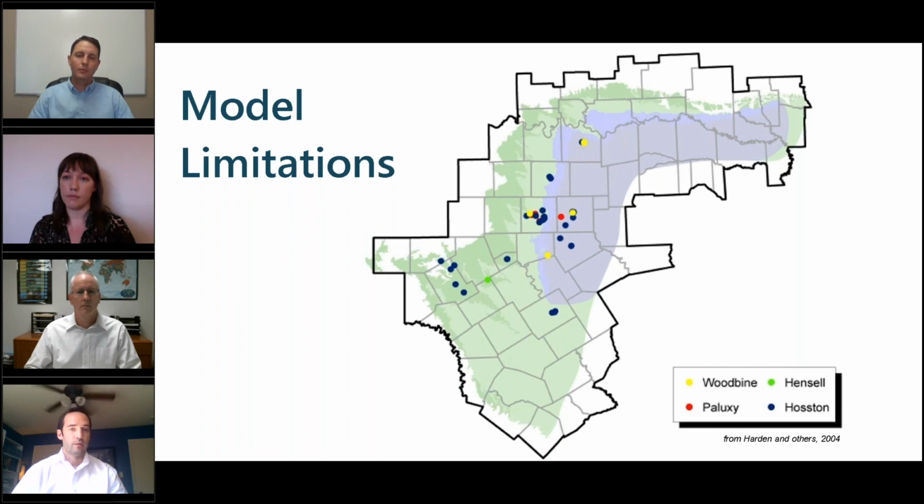So if the model is intended to forecast, say, the response of an aquifer to additional withdrawals that might affect the stage of surface water bodies in the area, then simulating a lake with a constant head is probably not going to work very well. It's probably not an appropriate boundary. You would need something more complex. And another example would be using a specified head boundary at a location where there's no source of water to maintain the head at that value you specify.